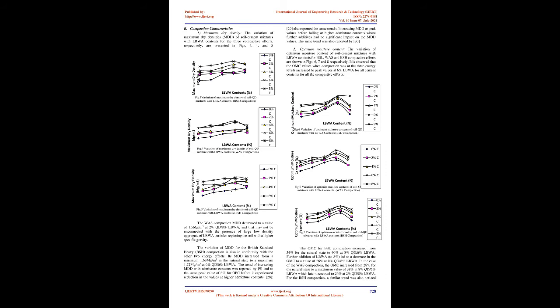The little amount of calcium in LBWA, 1.08%, to be used for the stabilization process was supplemented by the calcium present in a typical OPC, of 63%. The higher silicon and aluminium oxides in LBWA, also aided by the coarse nature of the quarry dust, will provide the required reaction needed for stabilization.